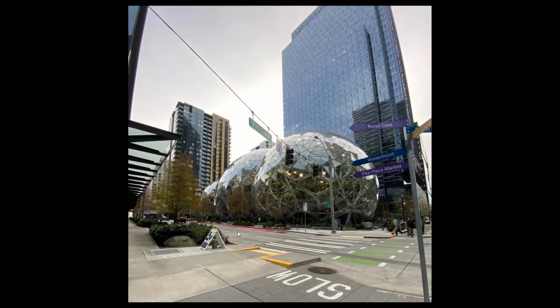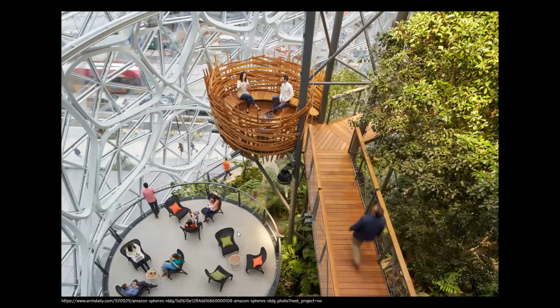For lateral stability, this building has a concrete core, which is one of the three types of lateral stability we've talked about. Just to review them, they are shear walls, like the concrete in this case, braced framing, which uses diagonals and triangulation, and rigid connections. And this is just an interior render, which shows the structure a little better than the images I was able to get.